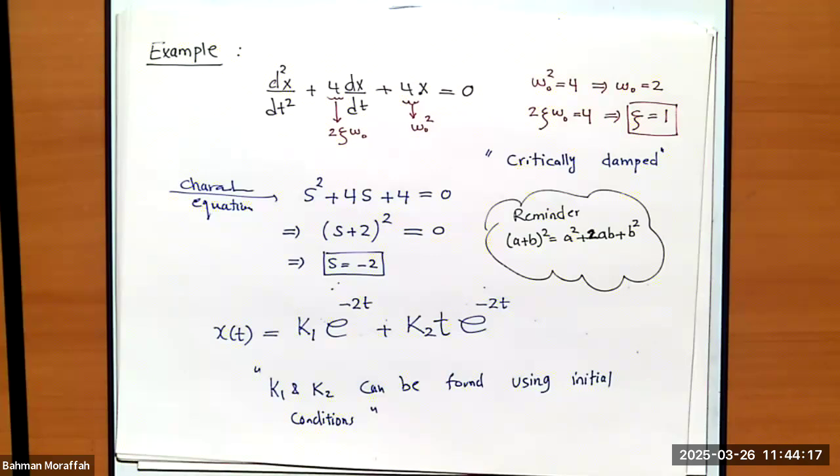So if I have a capacitor, I open it up. If I have an inductor, I short it out. And all I have to do is find a complementary solution. To find a complementary solution, I write the characteristic equation for the differential equation that I found and decide on the cases. And I'm going to decide on the type of the complementary solution that I have, right?